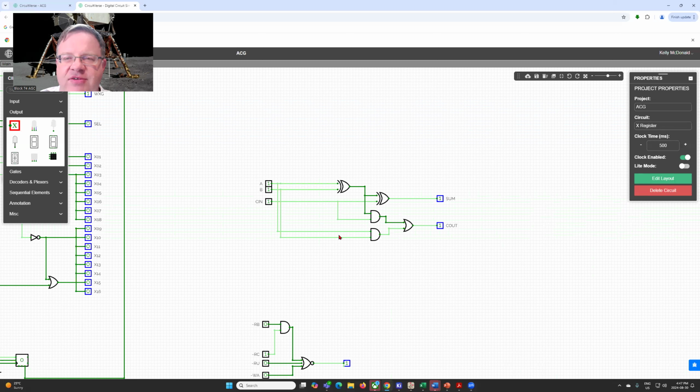So in the case of the Apollo guidance computer and modern computers, there typically is logic that's applied to try to predict those carry flags in certain subsections. So we'll look at, okay, of these 4 bits, should we produce a carry out of these 4 bits into the next 4 bits, and so on and so forth. Instead of potentially propagating all 16 bits in the Apollo guidance computer, if you break it into 4-bit blocks, you'd only potentially have to propagate it 4 times down.